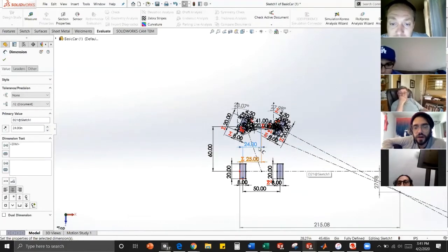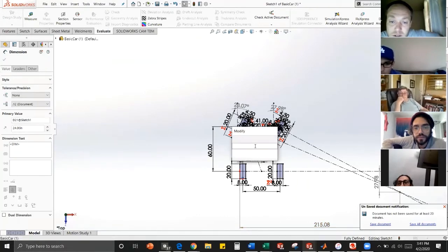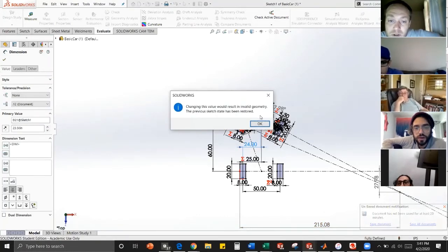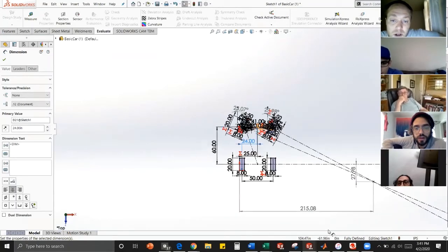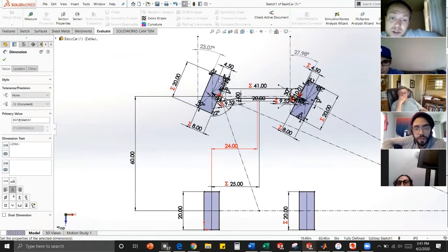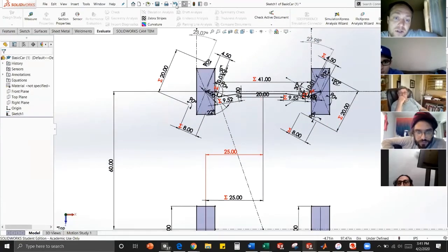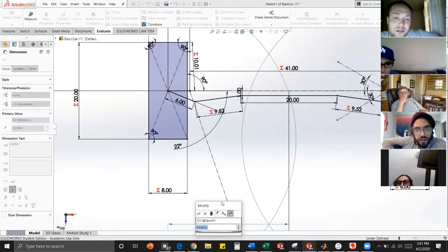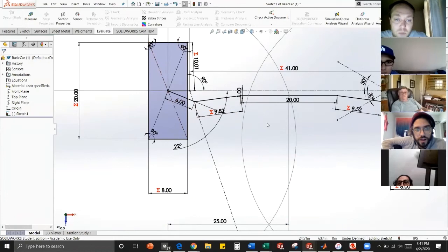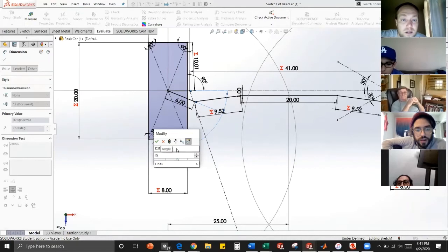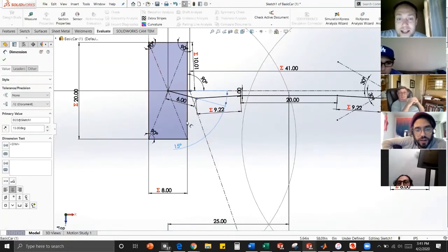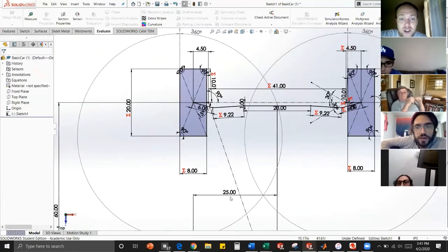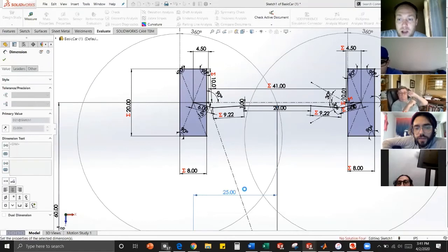So keep going. Go up through 23.5. Okay, so go back. You're still meeting behind the back wheels. So put this back at 25. Oh, what the heck happened here? Wait, chill out. The tire's not straight. There you go. Okay, good. Now what's the angle between the 6th and there? It looks like you lost that. Oh, it's right here. Make that lower. Make that like 15. There you go. So that's even more excess Ackerman. So try that. That'll help. So you'll meet in the front, hopefully.